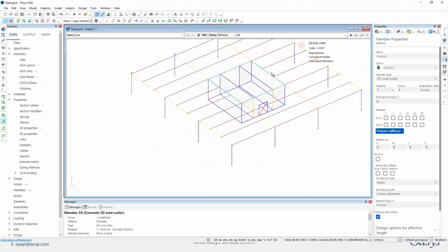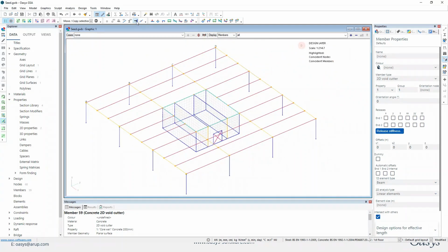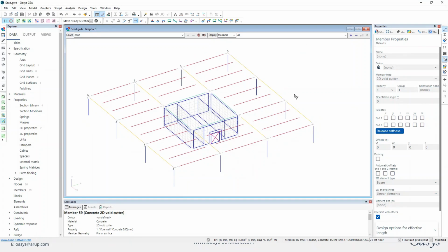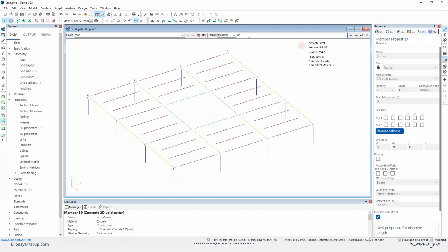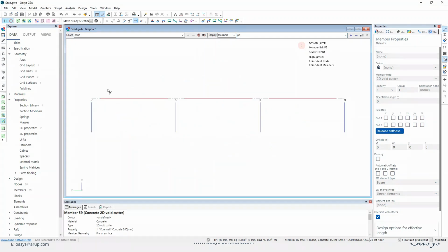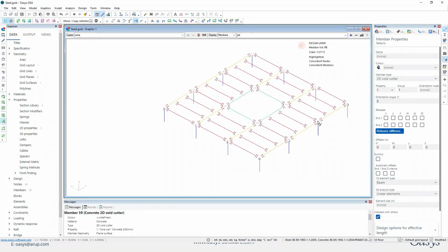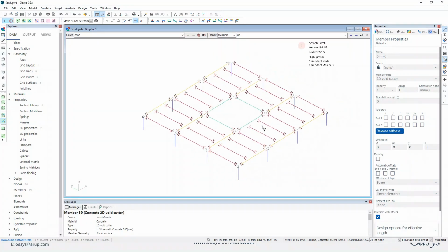Oh, also, of course, this is a steel frame. What we need to do is make sure that we have moment releases on the ends of the beams. So what I'm going to do, right, property beam, look from the side, select all those beams, and then just add in moment end releases in the major and minor axis direction, but not the torsional direction. Connections do have a torsional stiffness, and we don't want to destabilize the structure. Okay, all good.